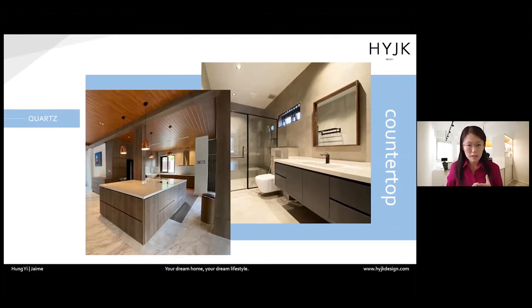For the branded ones, usually their material specs are much better. The component of the stone itself is much higher. So it's a man-made stone, and the stone component is usually 90+% for branded ones like Southstone and Caesarstone. Hafari has one that's very good also. Smart Stone is also 90+%. And most others from China are usually about 80+%, and the rest is like resin composite.